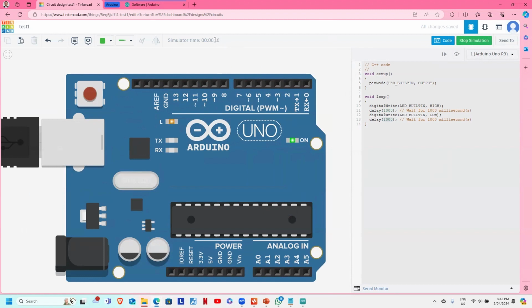It means this is simulating the time since the start of Arduino. For a simple circuit or less complex programs, this could be very similar to your system clock or the computer clock. But if you have a complex program that takes a long time and long compute power to get executed, the simulator time would be very slow compared to the real-time clock on your computer.